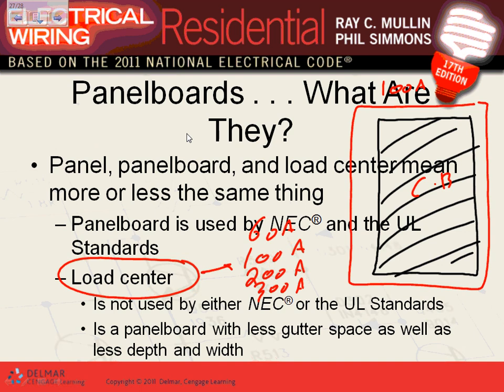If that was a panel, look what they do. I'm going to use a different color. They take a smaller space to fill with circuit breakers. So the question is, what happened to the rest? Why do you think they allow bigger gutters? This is called the gutters. They allow a bigger gutter around the circuit breaker, so you can maneuver all your circuits in three-phase and commercial industrial.